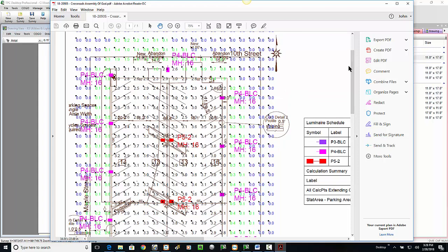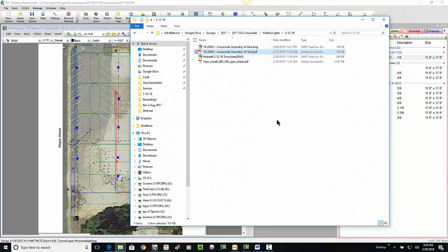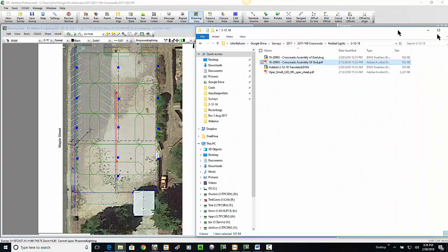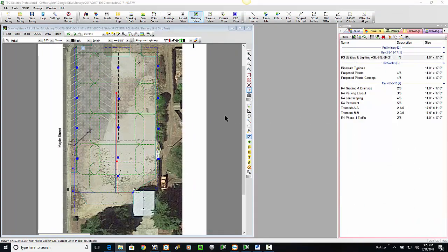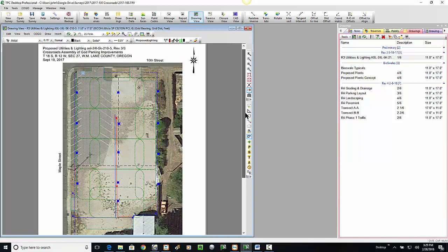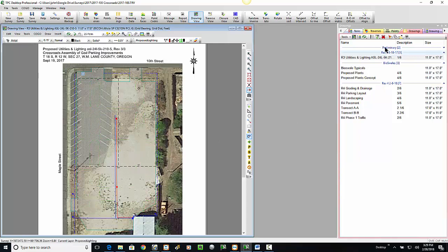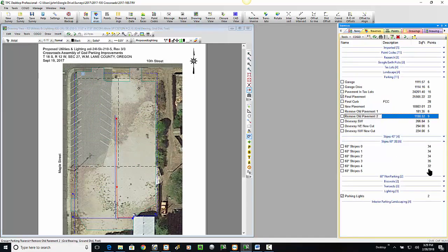So ultimately I'm going to want to go out and stake out these poles, and we're going to need to put in the underground. I want to do the underground lighting wiring with the water in the same ditch, so Gary only has to dig 1 ditch. And of course, I'll code which ones are deeper and how far apart and all that. So I'm going to turn off this last layer here, and I'll turn off my traverse that has the lights in it.